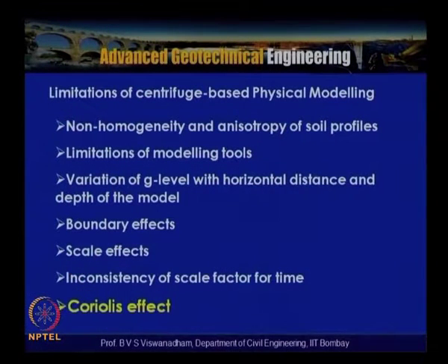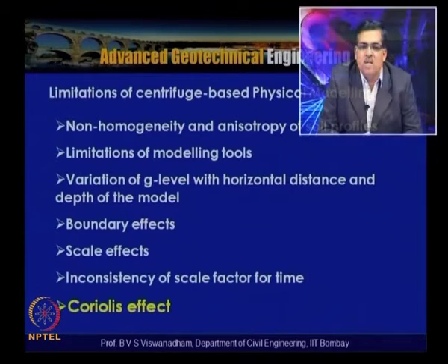Like any modeling technique, the centrifuge-based physical modeling technique also suffers from some limitations, like non-homogeneity and anisotropy of soil profiles being difficult to model, limitations of some modeling tools, the sizes and all those things required to be considered, and variation of G level with the horizontal distance and depth of the model.